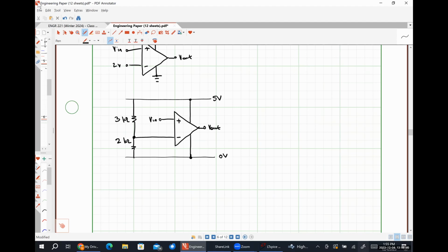Right, 30 times 10 over 30 plus 10. Same thing down here. Add those two together, 600 over 40, right? What's 600 over 40? 15. So 15 in parallel with 30 is 10.